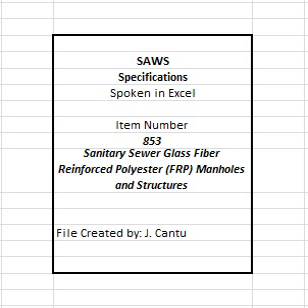Deeper manholes and structures, 6 feet, may require a minimum of 2 1/2 inches deep x 3 1/2 inches wide stiffening ribs, completely enclosed with resin fiber reinforcement. All fiberglass manholes and structures with a fiberglass bottom will have a minimum 3-inch anti-flotation ring. Manhole bottoms shall be a minimum 1/2 inch thick.